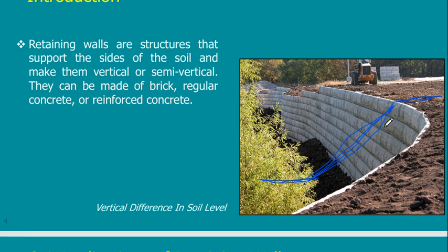You have taken before the stability of slopes. Slopes are my first choice. But in case I don't have adequate land and I need this area, I cannot, from here to there is the area used by the slope. I don't have it. So in this case, I will remove this slope and put this retaining wall. So retaining wall is my second choice because it is expensive, much more expensive than a slope. Slope is just